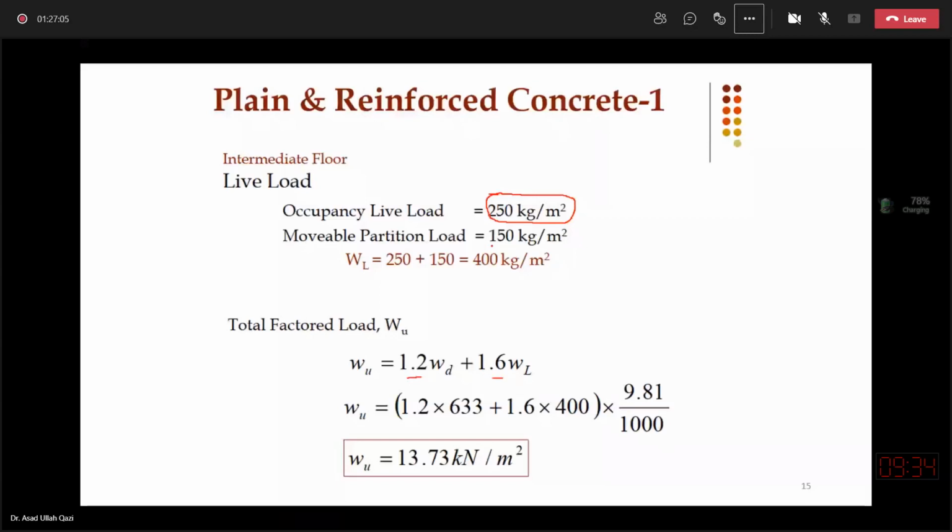The idea is to first calculate the volume of that partition. You know the thickness of the walls, their lengths from architecture working drawings. You know the height of them as well. So knowing the volume, you can multiply it with density. That will give you total weight of that partitions. Then divide that total weight with the area on which they are resting. It can be converted then into pressure.